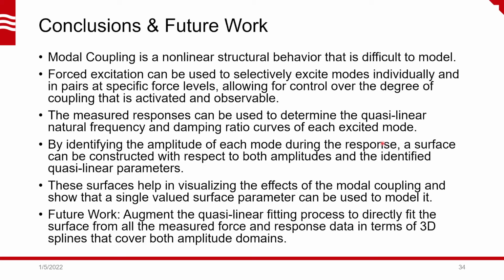And then by identifying the amplitude of each mode during that response, we can construct a surface with respect to both amplitudes and the identified quasilinear parameters. Visualizing these surfaces can help quantify the effect that modal coupling has on each mode, and it also represents a single-valued surface parameter that effectively models the coupling as well.